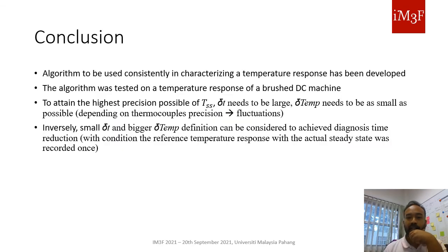So that's all. In conclusion, an algorithm has been developed. The algorithm was tested on the temperature response of a brush DC motor. To attain the highest precision possible, we need large time intervals and the smallest possible temperature resolution. But of course, it is limited by the fluctuations due to the precision of the instrumentation. And inversely, we can also use the fact that measuring only a percentage of the steady state temperature, if we have a reference, can be an interesting way to reduce diagnosis time.